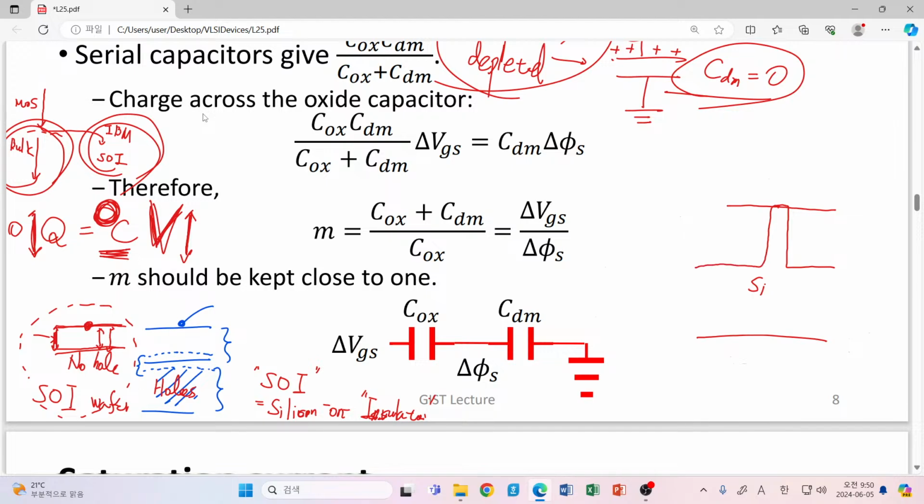Previously its shape was just a planar wafer. However, by introducing certain etching patterning, now they can introduce quite a thin vertical structure. So typically this is like 5 nanometer or around 10 nanometer. Of course this is not actually vertically thin, but instead, this is horizontally thin.